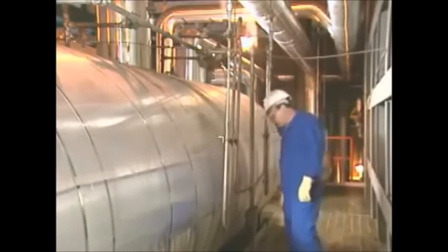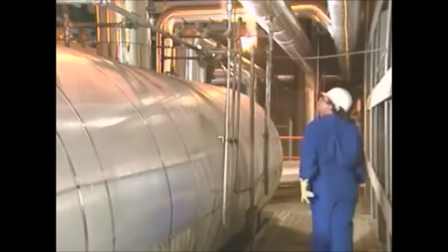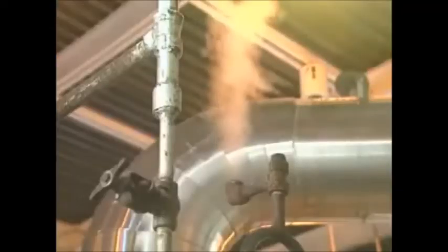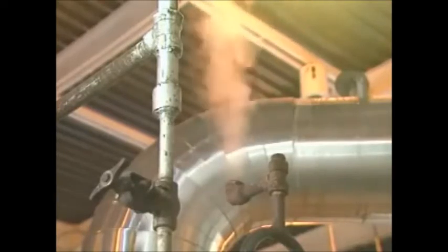That can cause a major loss of heat energy and fluid from the deaerator, which will decrease plant efficiency. Also watch for insufficient venting. That will allow oxygen and other gases to remain in the condensate and feed water system and cause problems downstream.